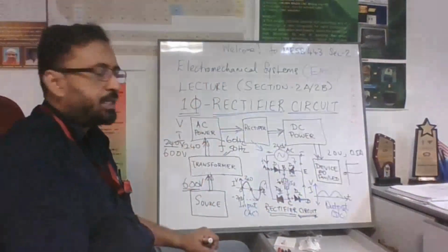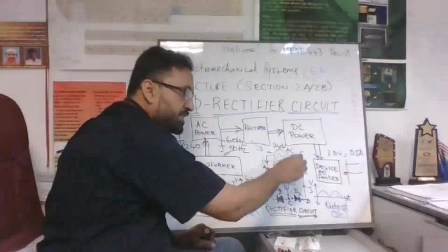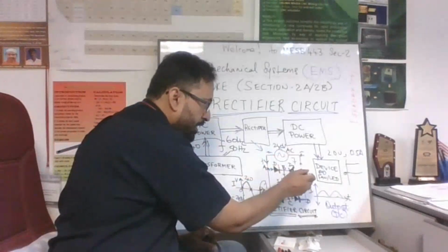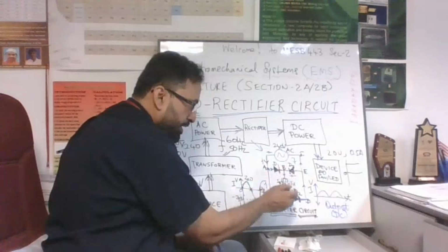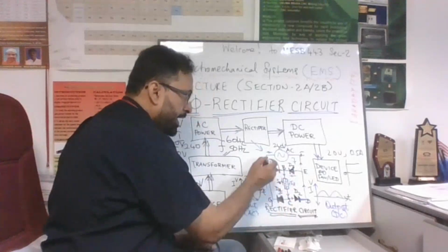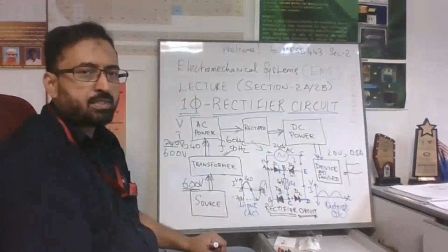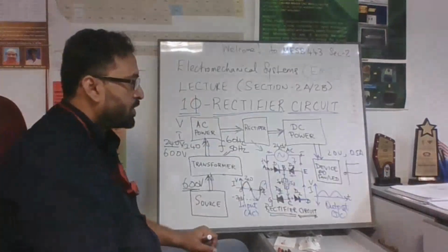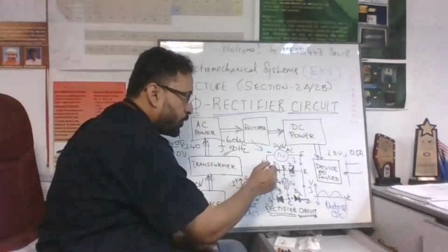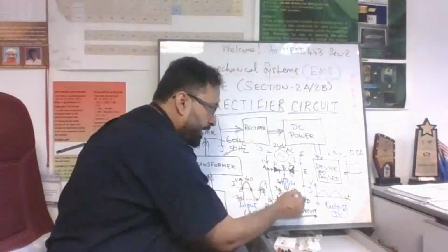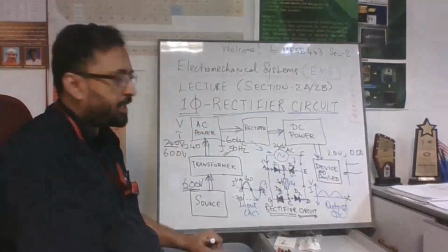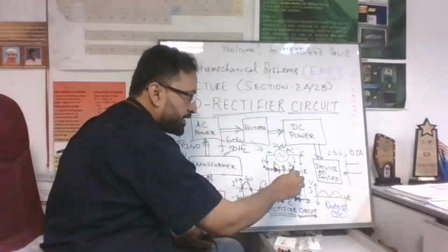During the negative part of the cycle, the current reverses direction. So the current from F, E goes to B, C, G, A, and then it completes the second part of the cycle. So every time one half cycle passes, the current flows through diodes D1 and D2. During the reversal of the alternating current, the current flows in the opposite direction.